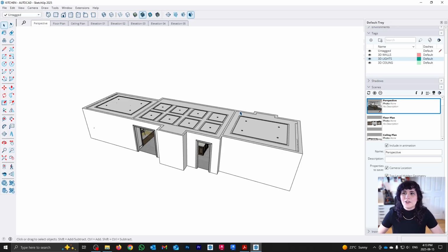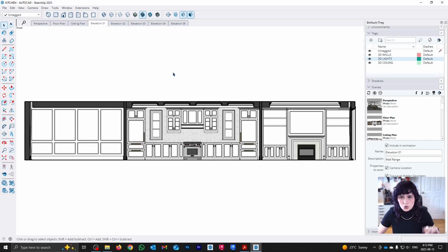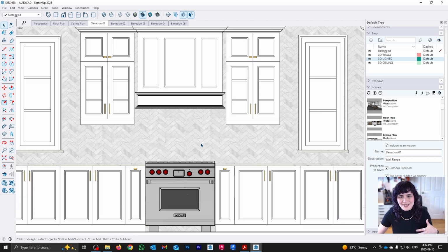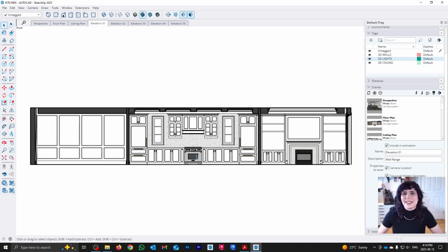Well, the setup is going to be very similar as if you would just be working in SketchUp. You want to build your model with maximum level of detail. You can use your tags, you can use your groups, you can use your components. But then the most important thing is that we are going to want to set up our construction documentation views in SketchUp. That means switching to parallel projection, setting up sections and whatnot. Basically, you want to think about this like you want your SketchUp drawing to look as much as possible like an AutoCAD drawing. Right? Don't worry about style things because things such as materials are not something that is recognized by AutoCAD, so you don't have to worry about setting that up.